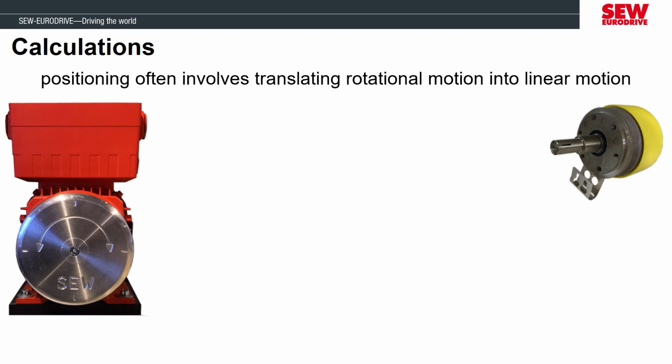You can connect numerous types of encoders to the MOVIDRIVE, and they can be different resolutions. Having different resolutions, though, could make it more challenging to fine-tune and troubleshoot the positioning accuracy. So the MOVIDRIVE will always equate one rotation of the motor encoder as 4,096 pulses. Even if we were using a common encoder resolution of 1,024 pulses, the MOVIDRIVE will automatically upscale that to equal 4,096 pulses per rotation to make the scaling consistent.